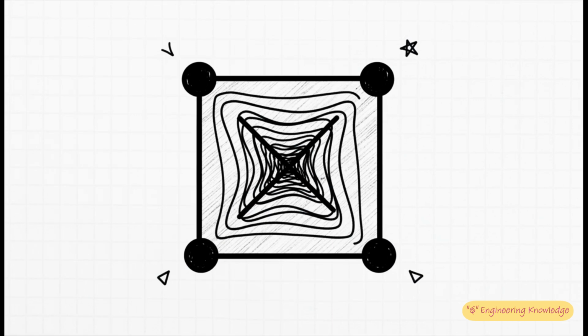Now, here is the really crucial part. FEA relies entirely on discretized calculations. What does that mean? It means the computer is only calculating equations at very specific points, which we call nodes. For all the empty space inside the element itself, the values are just guessed or interpolated based on the element's specific mathematical shape function. Because we're only calculating at these specific points and interpolating the rest, the shape of the puzzle piece, our element, is absolutely critical to finding the truth.